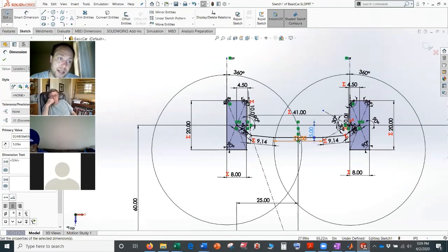There's also the downside of front steer: if it's front steer, it's exposed for Baja, right? So it can get hit with bumps. It's not a big deal for formula, I don't think. But if you can package in front steer, you can get tighter turning. It's just harder to package in because it puts the steering rack right next to the driver's feet typically.